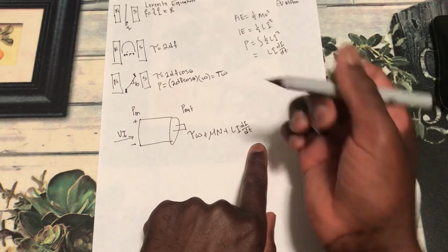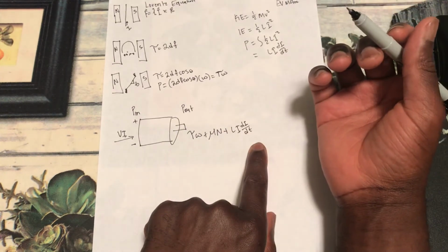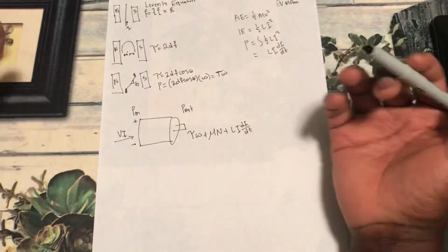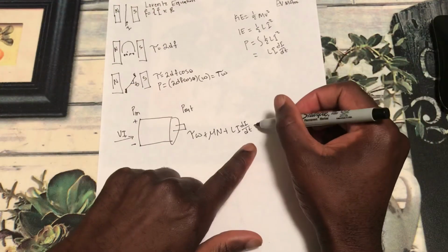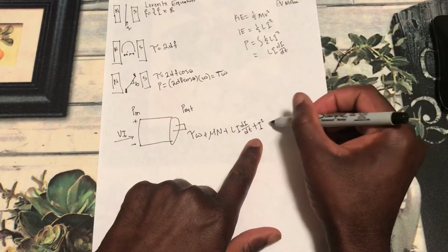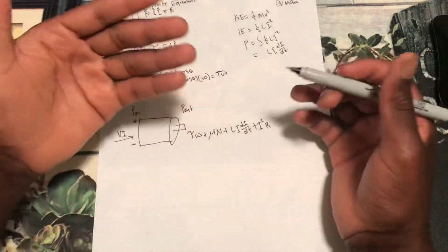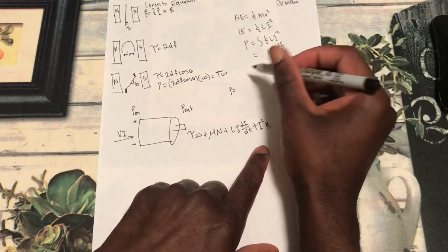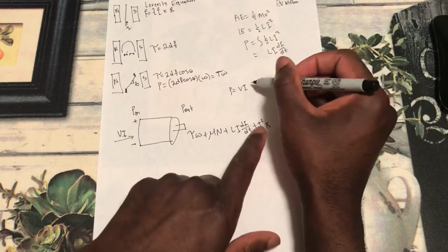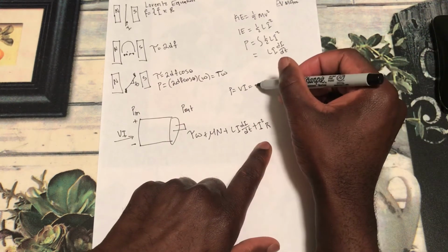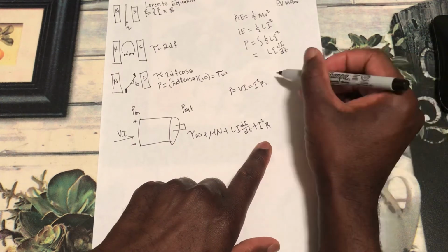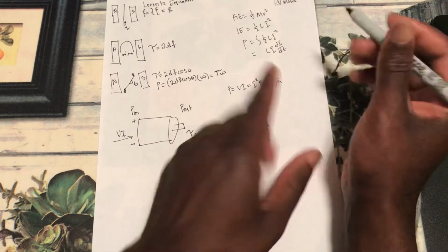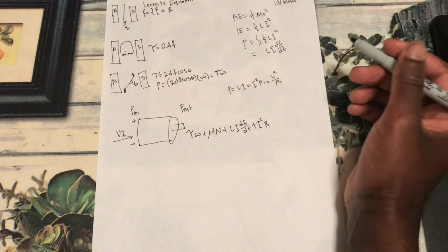We also know that we will have some energy loss due to our resistance, because again, current will flow through the wire, and the wires produce some kind of resistance, so we'll have some power loss due to resistance, and that's simply I squared R. And this is just from the normal equation for power, which is P equals VI, which also equals I squared R, which also equals V squared over R. And we just use one of the components that has resistance.